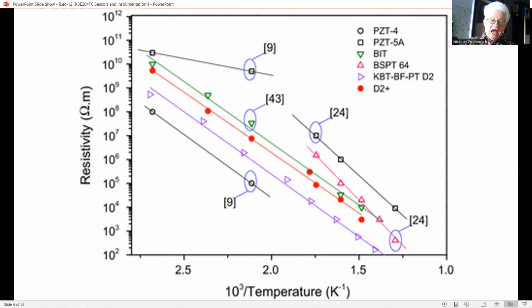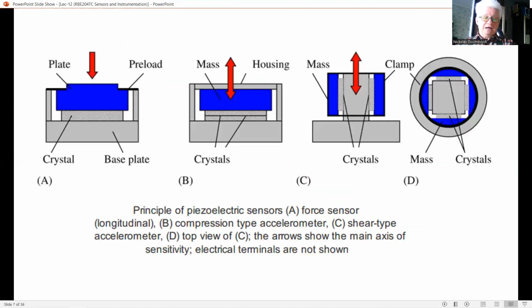Fortunately, as long as these charge changes are slow, they do not limit the applicability because of the previously discussed intrinsic high-pass character. Usually, the elements of the transducer are kept together by clamping rather than gluing. A consequence is that the crystal becomes preloaded.